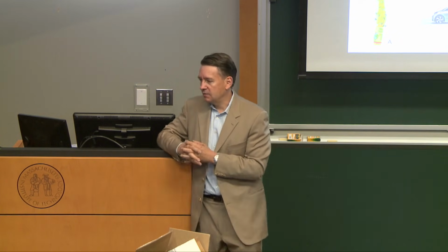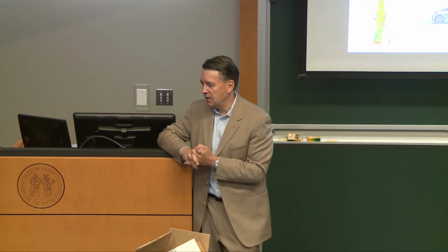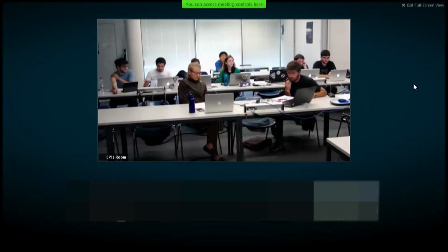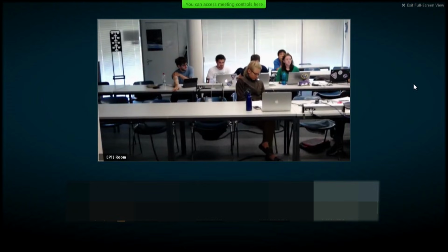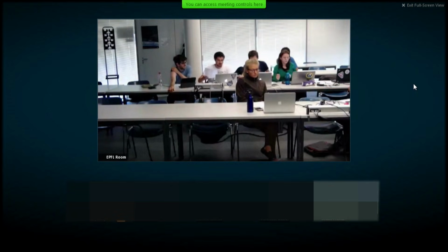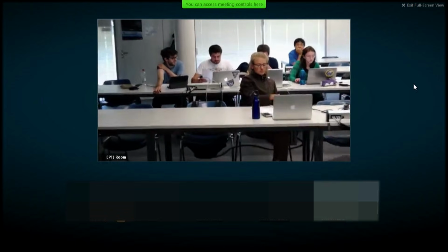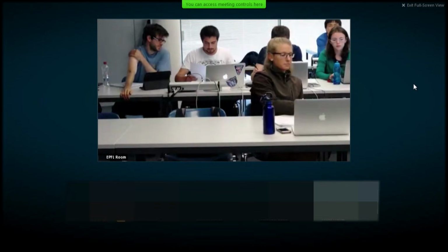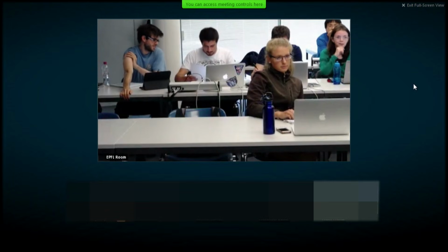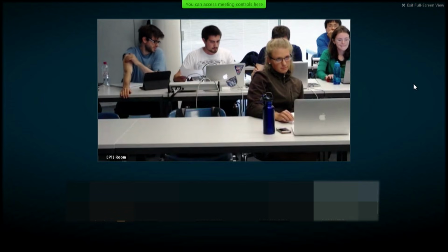Okay, EPFL, the i3, any other requirements there? So we have 4 to begin with. The car shall rely on electricity as the unique source of power. A second one is the autonomy, so the car should drive at least 150 kilometers in city driving conditions, like the cycle we just talked about. As a third one, the car shall carry 4 to 5 passengers of average build. And to finish with, the car should be fully recharged in less than a given amount of time.